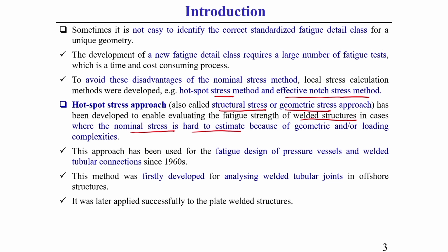Due to the complexity of the geometry as well as the complexity of the loading, the nominal stress is not able to predict the fatigue life, and there we can use this hot spot approach. This approach has mainly been used for fatigue design of pressure vessels and welded tubular connections since 1960. It is a very old process.